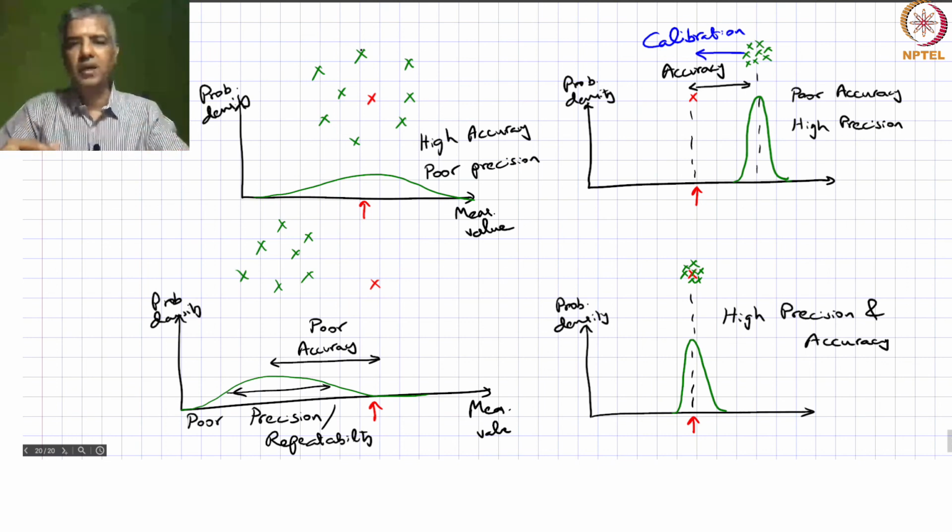Okay, there is a very low level of repeatability in your measurements. Every time you do it, it's giving you a different value. So there's not a whole lot you can do from a sensor perspective about something like that. But what you could possibly do to deal with it is, instead of making one measurement, you make 10 measurements and then you take the statistical mean of those measurements and you say, okay, that is the value that it should correspond to.